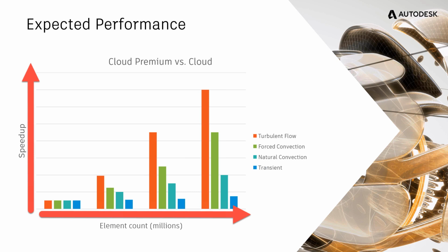That's the general mode. So if it were me as a user, if I had a turbulent flow model, valve, external flow, it doesn't matter, and it had a pretty large element count, I would test it out and see what I got, as a tester. And by the way, because it is a completely different solver, the answers are never going to be identical, but they should be very similar. All the testing shows just a couple percentage points off for exact meshes, difference in the solution. So you don't have to worry about that.